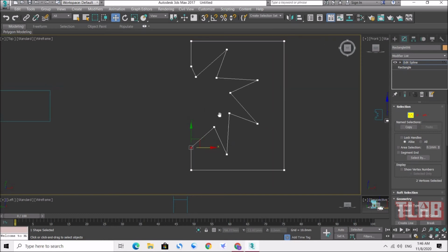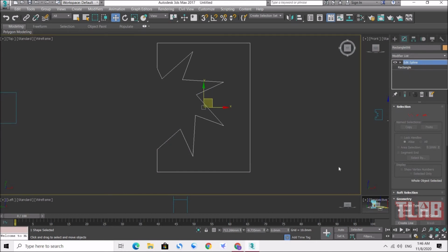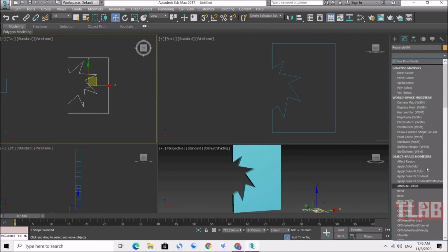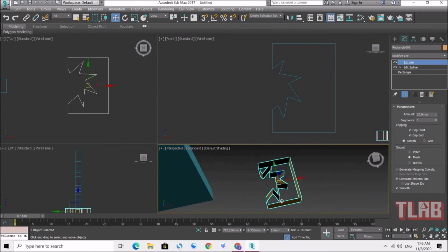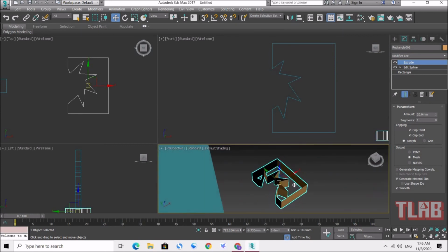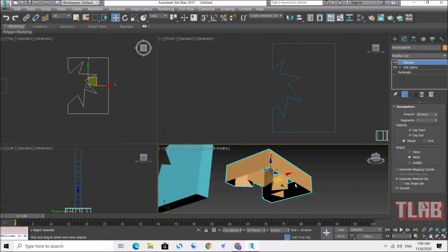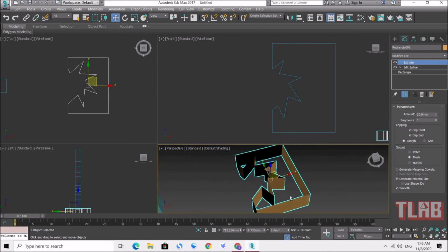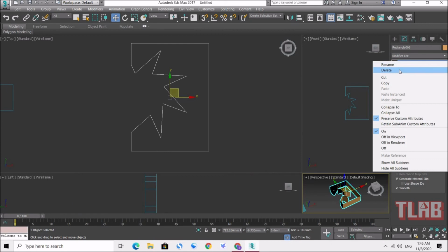Why do I need to do that? Because if you don't do that, let me show you. Just see, select the object, modify list, Extrude. Then you can see the model becomes like this, you can see the model, but just the outline is solid. But the face, the top and the bottom, you cannot see solid. So that's the problem. So remember. So now, Extrude, I delete first.